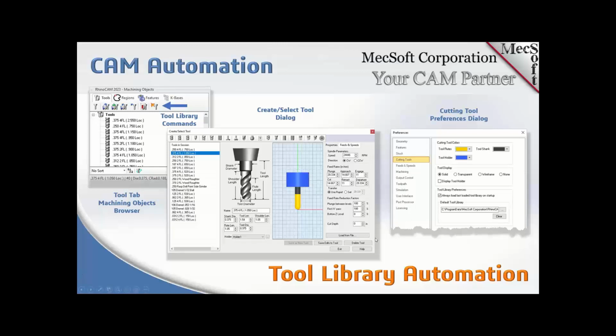But what I have on the screen here is, if I start on the left, I'm just going to name the dialogues and I'll go into a little bit more detail. On the far left, you see what we call the machining objects browser. It has 4 tabs: a tools tab, regions, features, K-bases. This is typically located at the bottom left corner of your Rhino display in the RhinoCAM machining browser. This is the bottom portion. And here's where you can load your tool library in here.